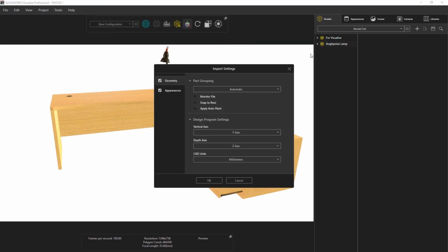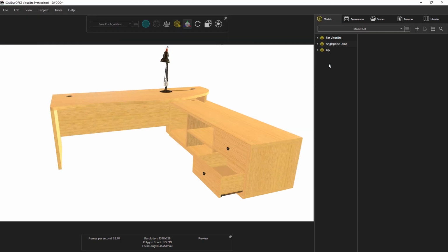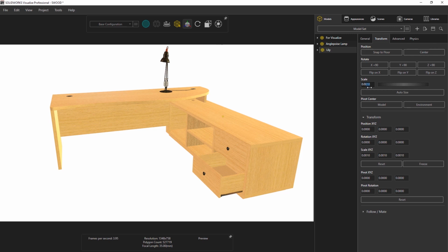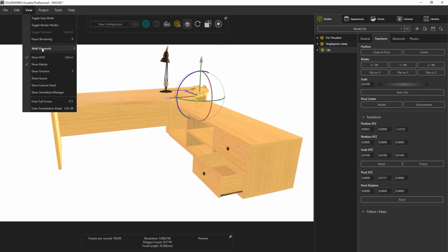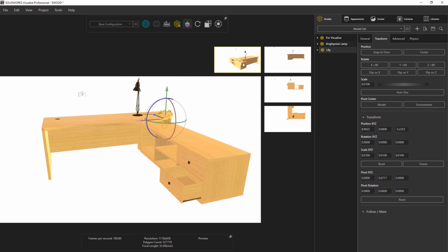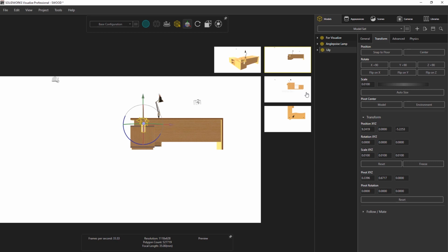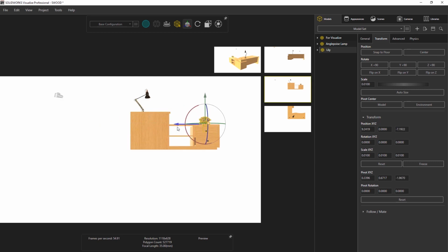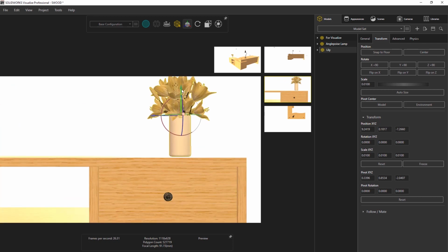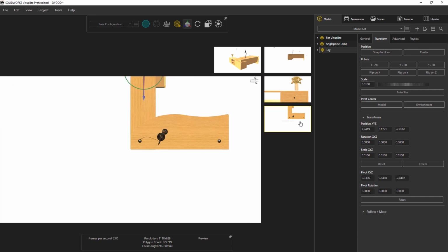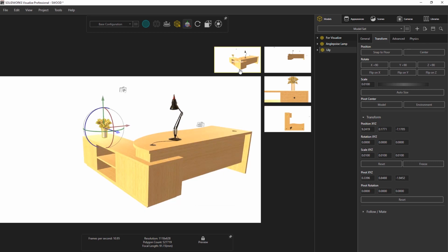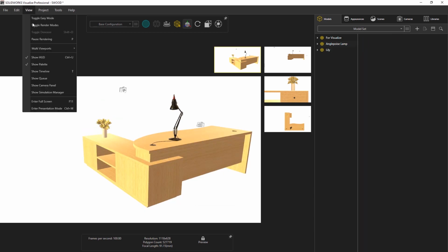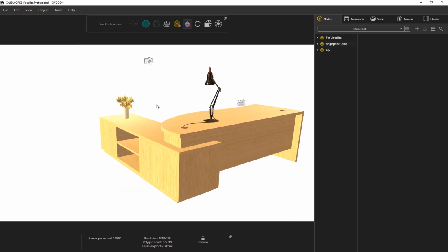Models like these are good for non-engineered parts such as flowers that other programs are more inept at creating than SOLIDWORKS. They can also include standard appearances that are imported with the model, so you don't have to do any more work. To move this around with the object manipulation tool, it can be beneficial to view 4 orthographic viewports rather than just having to rotate.